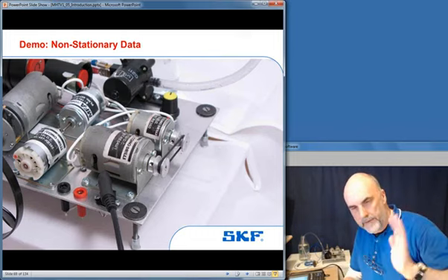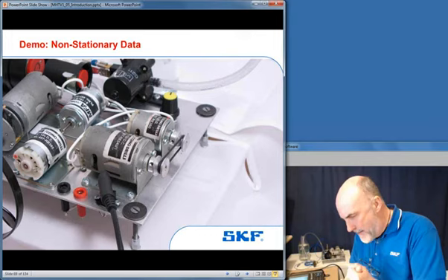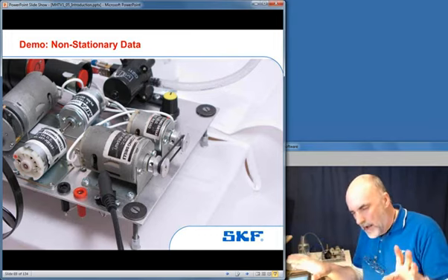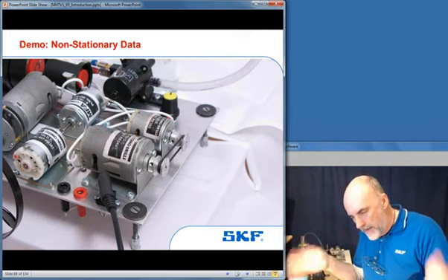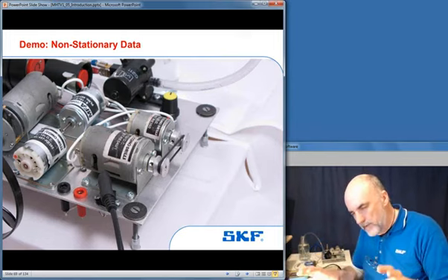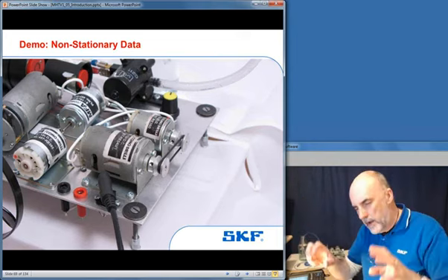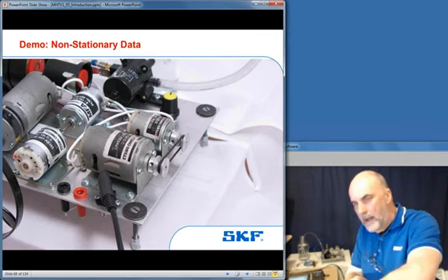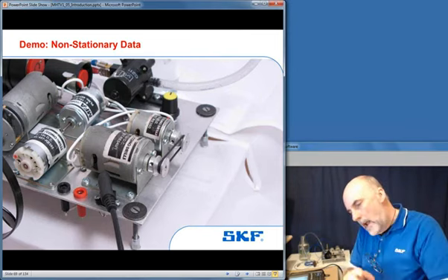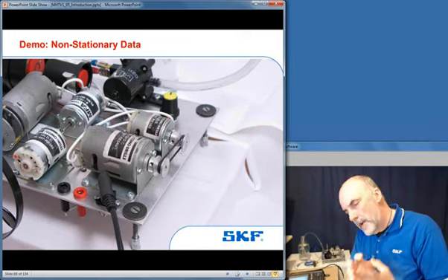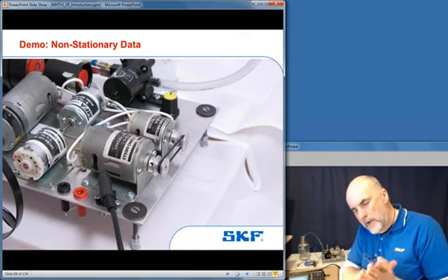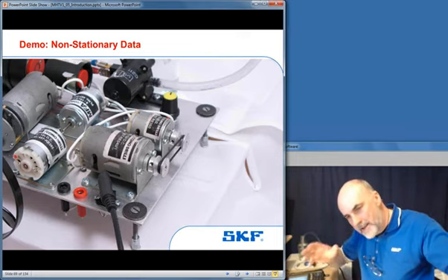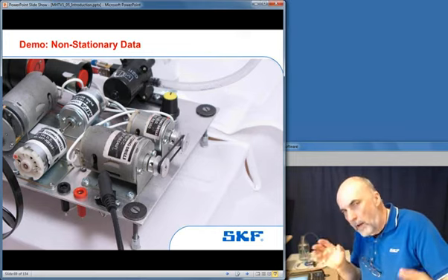When you go on your holidays and fly on an aircraft, just listen to what the engines are doing, especially a twin-engine aircraft. If you listen carefully and feel the vibration of your seat, you can feel the levels go up and feel the levels go down as those 2 engines interfere with each other, and that can be over a 5-second period. So one way of answering the question of how many averages is that you should be throwing in enough averages to cover that time period, and that time period can be quite long.